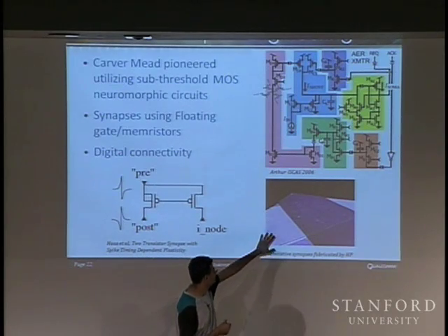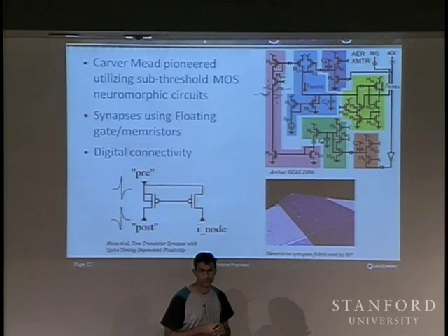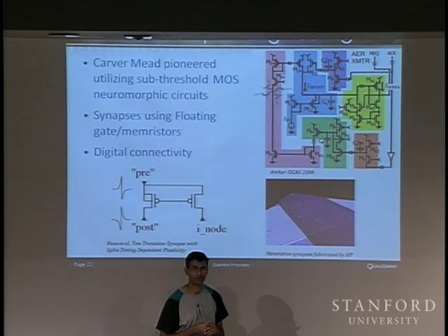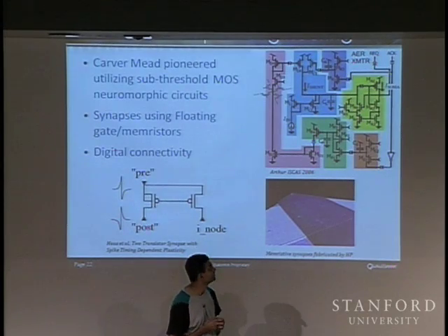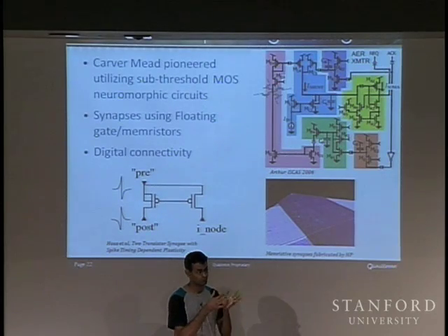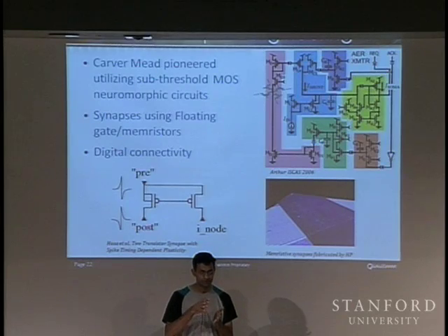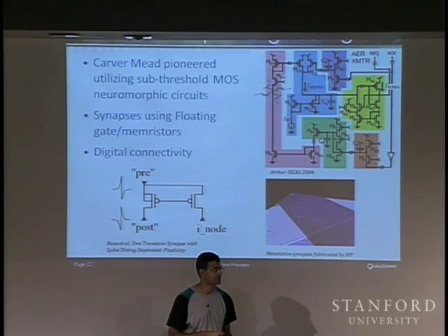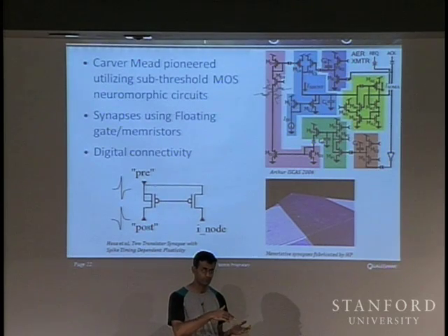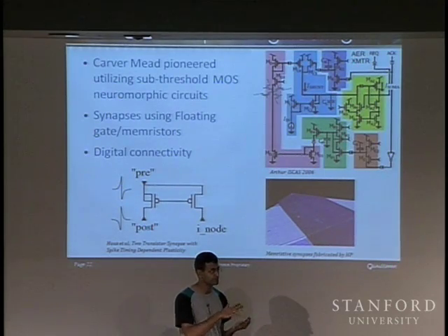Here's a picture of the memristors that were fabricated by HP. They've reported on a lot of interesting ways to use them. They seem to be drifting away from calling them memristors and calling them memristor switches, because they seem to be more like atomic switches. They switch really quickly. So they're having trouble making them switch slowly, which is what we need. So they form good digital memories. They don't form good analog memories, which is what memristors are supposed to be.